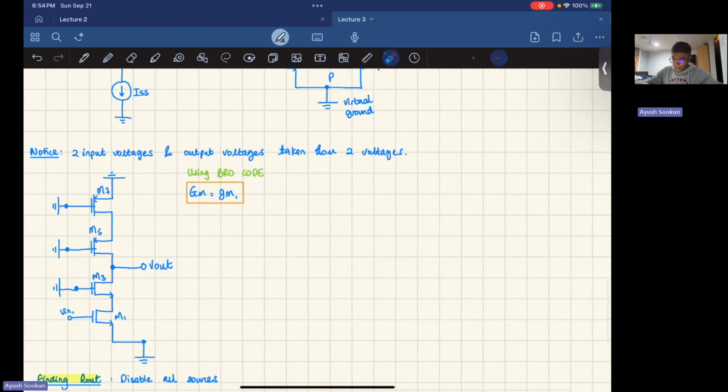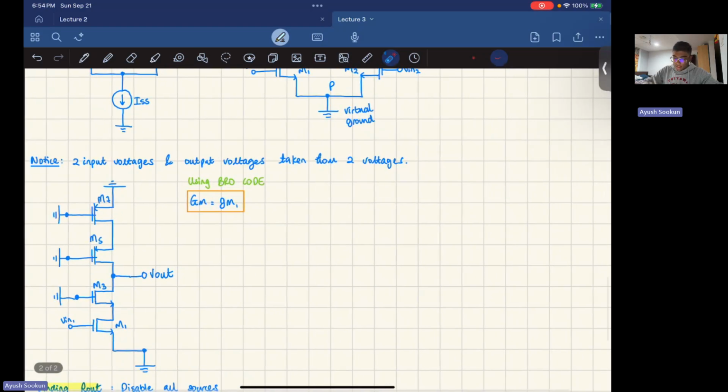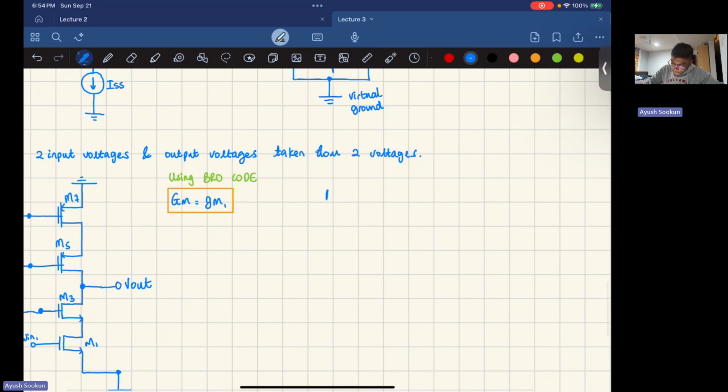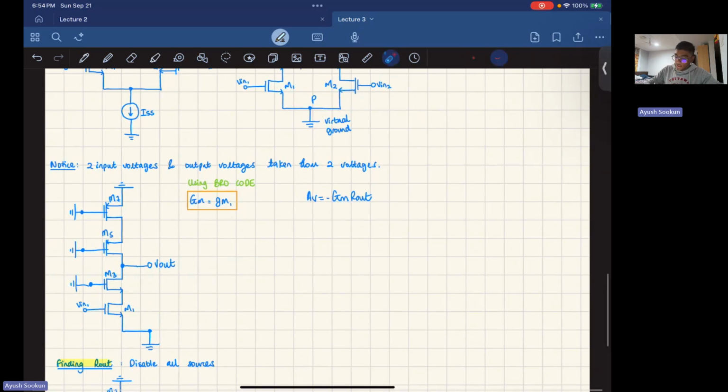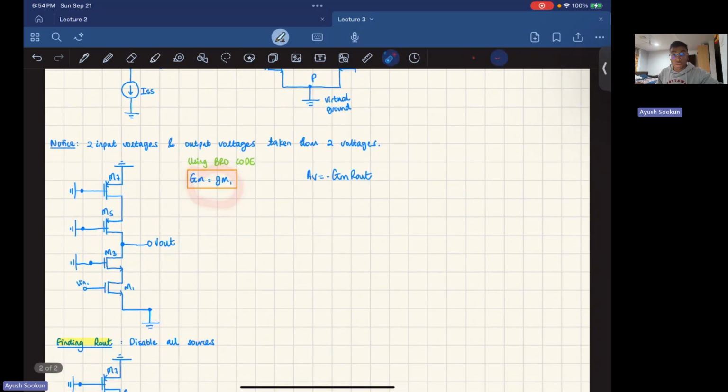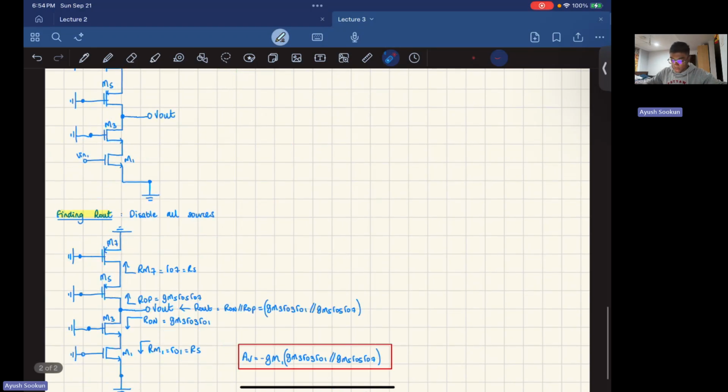Okay. Now, what is the gain equation? Gain equals minus gm R out. Now, I'm not going to show you how to calculate gm. gm is going to be equal to gm1 using the bro code. I never calculate my gms. If you do not know what the bro code is, go watch lecture 2. I'll explain it in there. This saves you probably like 10-15 minutes on a final exam, so go learn it. This is how you calculate gm, bro code.